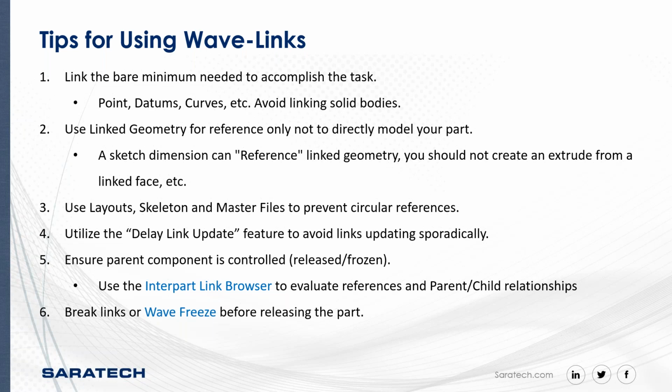Break links or use the wave freeze before releasing a part. So again, if you're releasing a part, you want to make sure you're breaking all those so you have something frozen, something static, rather than something that can be changed after release. So that can cause some issues. So best practice is to freeze or break those links.